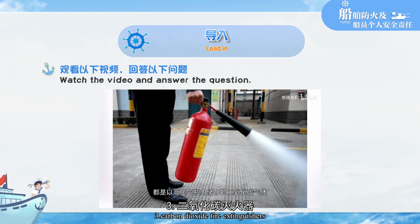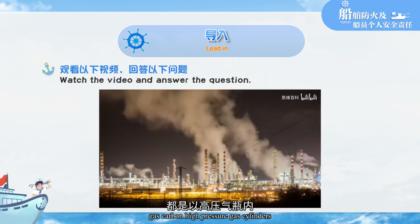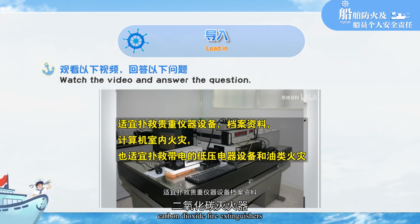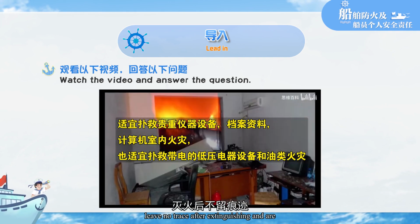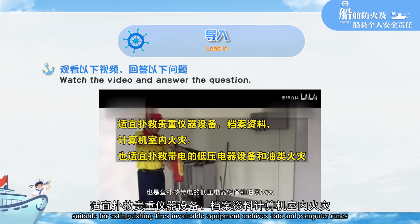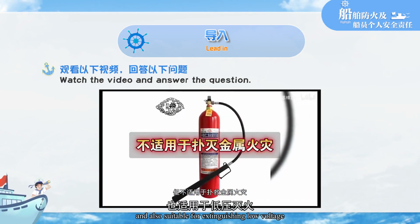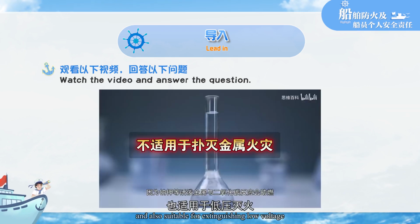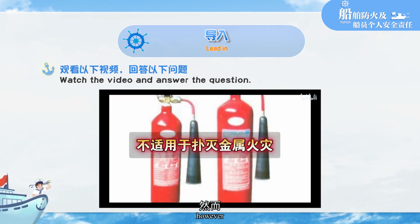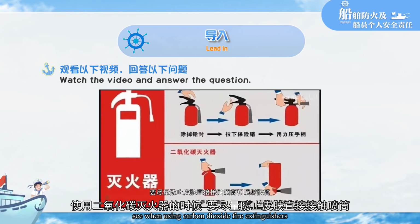Carbon dioxide fire extinguishers use carbon dioxide gas stored in high-pressure gas cylinders as the extinguishing agent for extinguishing fires. Carbon dioxide fire extinguishers leave no trace after extinguishing and are suitable for extinguishing fires in valuable equipment, archives, data, and computer rooms. They are non-conductive and also suitable for extinguishing low-voltage electrical equipment and oil fires with electricity. However, when using carbon dioxide fire extinguishers,